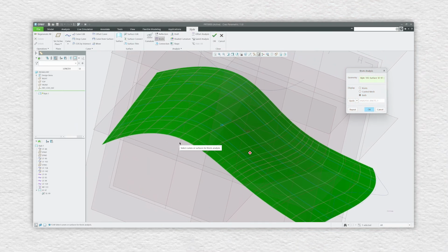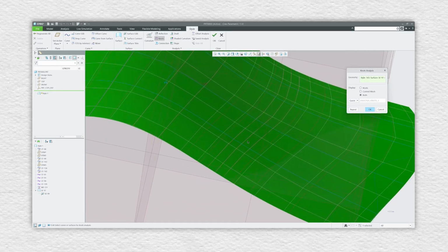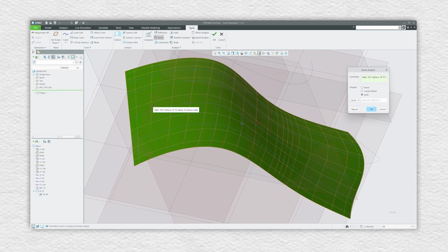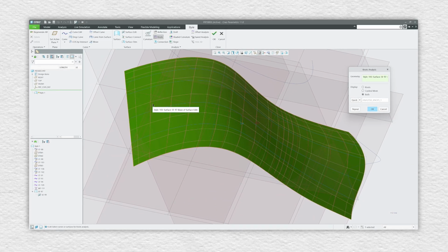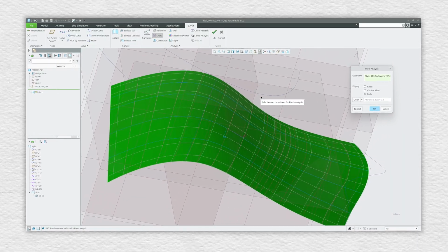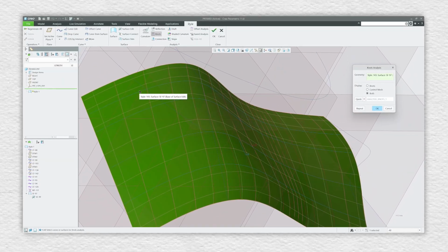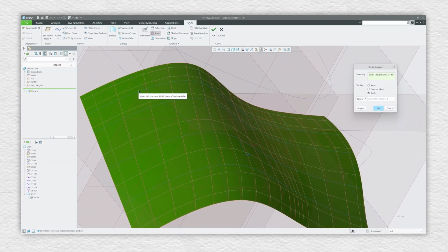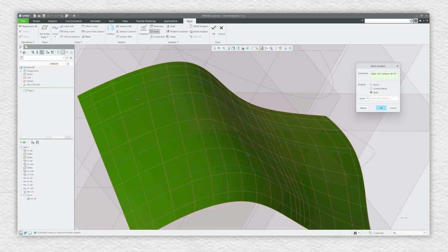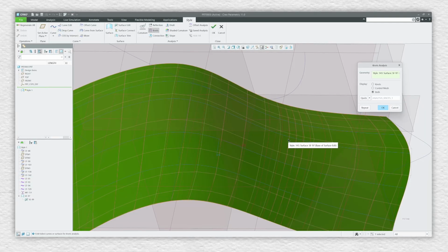Parametric. This tool helps you to visualize the internal structure of curves as well as surfaces, specifically the knot points, which are key parameter values that define how a spline or a surface is mathematically constructed. These knot points act like internal breakpoints where different segments of the curve or surface are joined. While they don't show up as a sharp corner in the model, they play a big role in how the geometry responds to edits, control point movement, and continuity.